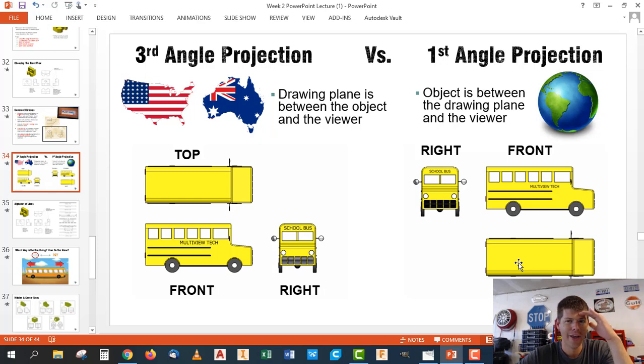I thought, whoa. They actually do know what they're doing. Before you guys send them an email and call them out on their drawing techniques and look stupid, here's what's going on. And so I had to explain to him that they're doing first angle projection. You're in the United States, so you're used to third angle projection, and you guys are going to get into this back and forth match where you both try to tell each other you're wrong, and technically you're both right. So if you ever receive a drawing from someplace else in the world, you probably will see that their views are switched because they're doing first angle projection instead of third angle projection.